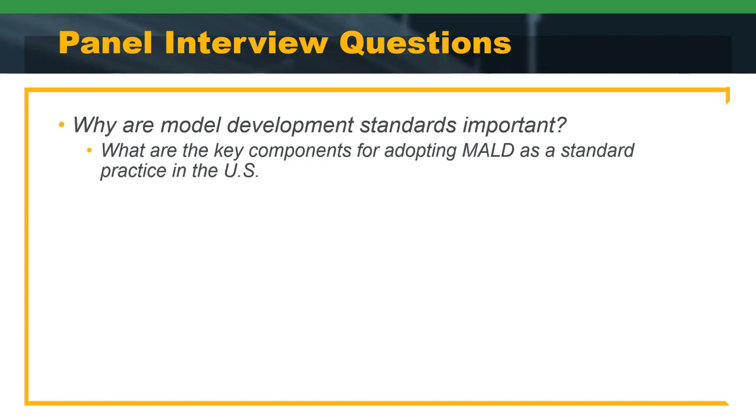And then you're going to have a level of development tool that's going to communicate basically the authorized uses. And then there needs to be a way to organize the information within the model and assign that level of development to the individual elements. And that's your model progression specification, or whatever you want to call it. It's basically an inventory of the model organized by object type.